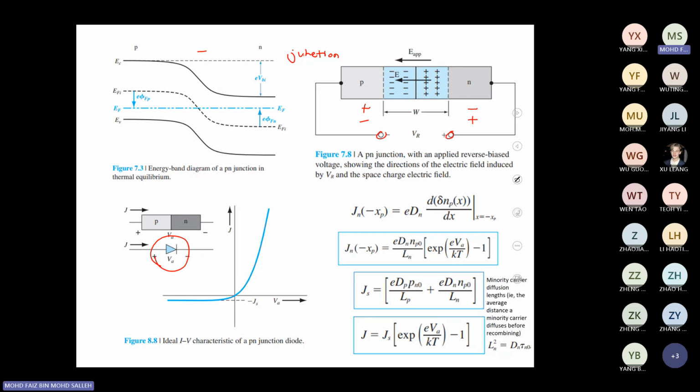Reverse and forward bias. And if you measure the IV characteristic of the diode by applying the voltage, you can get this kind of line. And here is not zero, because you have the reverse bias current, the leakage, which is very small. So you can make use of the diode as a one-direction current flow, and also use it as an on-off switch at the threshold voltage.